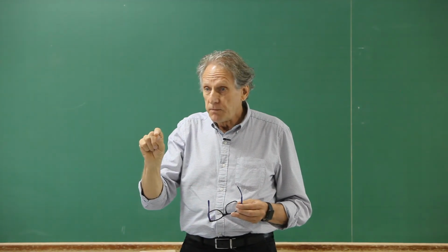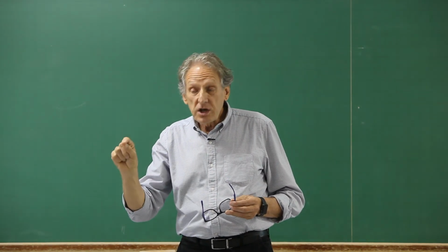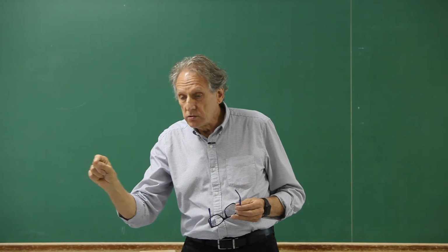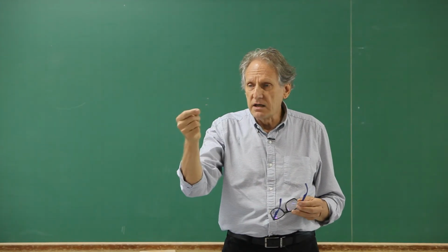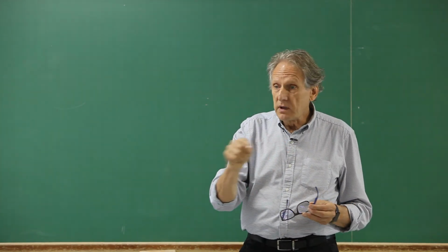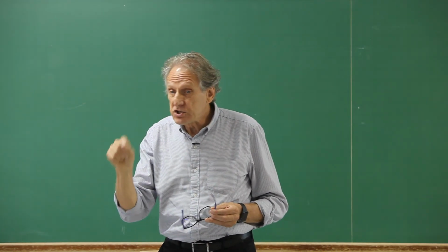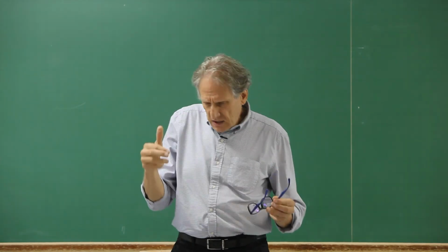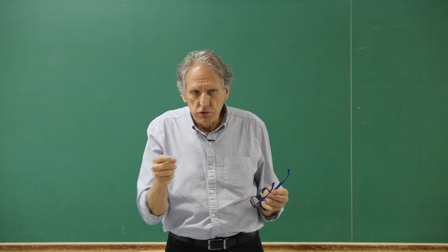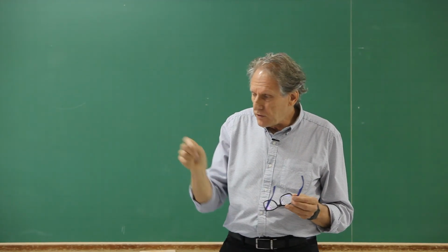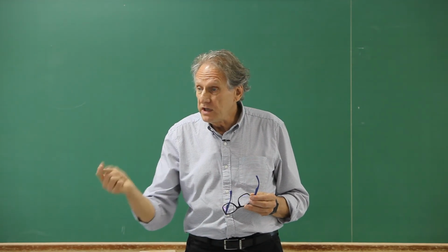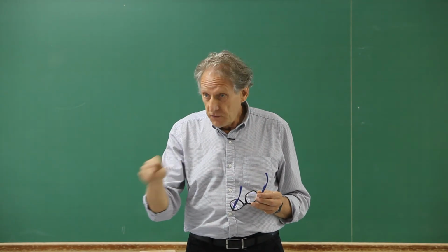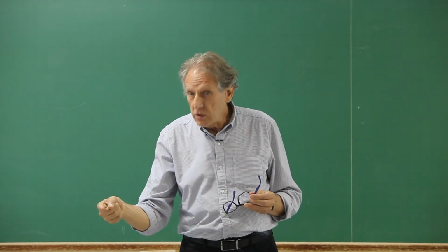So you can change time for each equation, say momentum in X, Y, and Z, energy, but you can also change time in each cell of each equation. Of course, it is kind of difficult for you to choose different time steps for different control volumes in each equation. But if you want, you can do that.